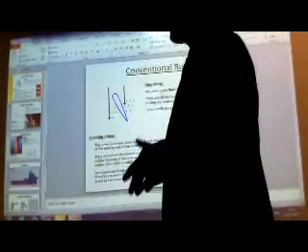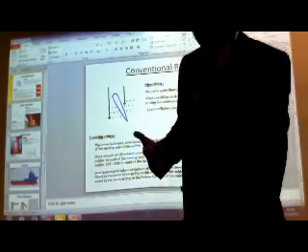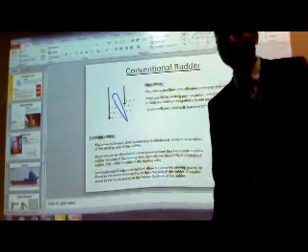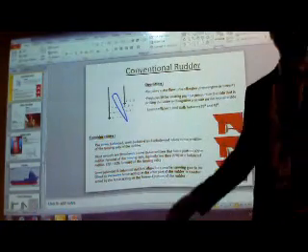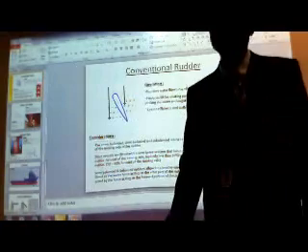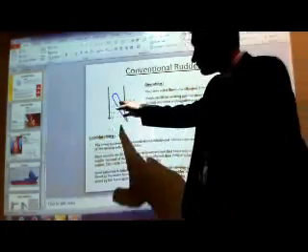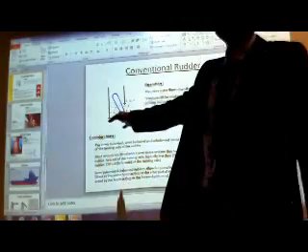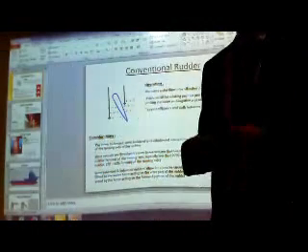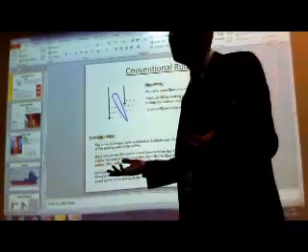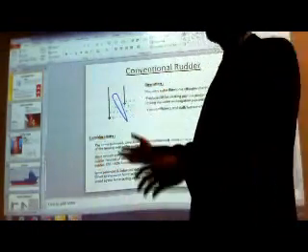What we want out of a rudder is maximum lift. We try to maximize the lift out of a rudder. That is what we want, because we use this device to do what? Control the direction of the vessel. We do not want unnecessary drag here. That is minimizing the efficiency. But you can't help it. It comes with it. Yes?